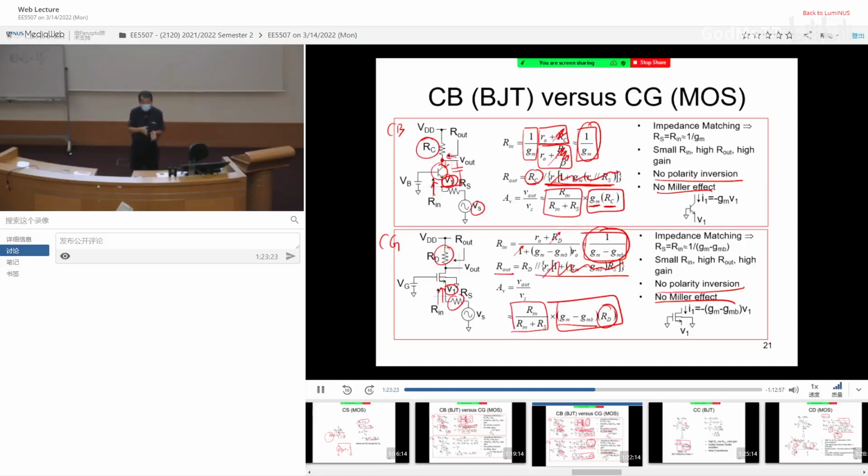Now, if you are talking about a normal signal in the lab, let's say an audio signal, from the audio signal source you want to maximize the voltage that gets transferred. You don't care about power. I just want to get this voltage amplitude. I don't want to attenuate it. I want to maximize the transfer. Then you want the input resistance to be infinity, so you don't have any attenuation. You get the point? In that case, you are dealing with a voltage signal, not power. Therefore, we maximize the resistance. So everything comes down to what kind of source you are dealing with.